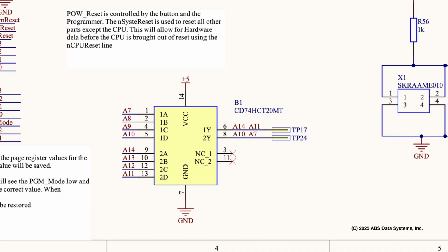In order to achieve the address resolution that I wanted to implement, there were not enough inputs into the CPLD. To accomplish my goal, I looked at the address lines and determined that A0 through A6 and A15 were crucial. Then I also looked to see that A7 and A14 were always in the high position. So I didn't need to look at them on an individual basis.